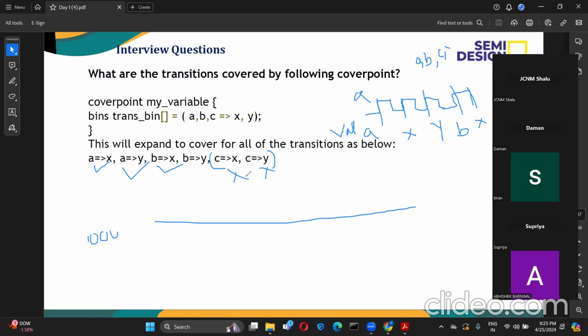Yesterday we saw some code, right? Which things didn't get covered, it showed as not covered and the percentage was 0 there. Then you will understand that this scenario is not covered. So then you have to go to the test case and see if there is any way you can give a stimulus in order to cover this scenario. That's how your analysis will be. So if the coverage is 0, then this is a miss case. You need to check the test case again in order to get the coverage. Yes, ma'am, correct. Thank you, madam. I got it.